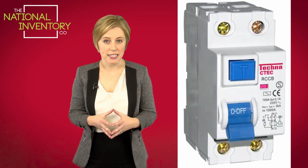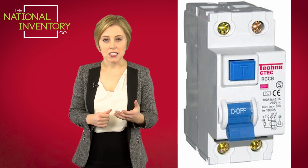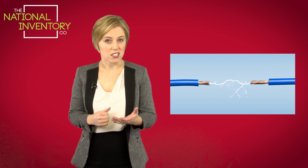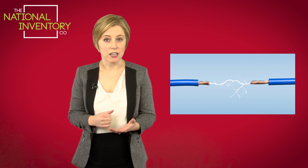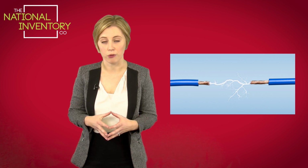During your midterm inspections, make sure you do a visual inspection of the property to ensure there are no cracked electrical sockets. Make sure that your property has an adequate RCD protector. RCD stands for Residual Current Device. It's a life-saving device which is designed to prevent you or your tenants from getting a fatal electric shock if you touch something live, such as bare wire or a cracked socket. It can also provide some protection against electrical fires. RCD offer a level of personal protection that ordinary fuses and circuit breakers cannot provide.